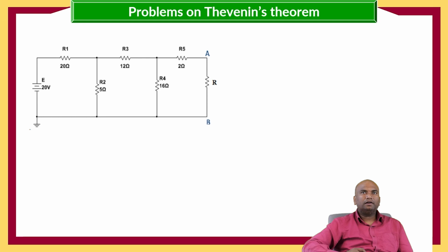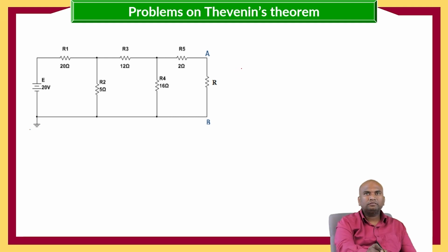Next, we need to calculate the Thevenin's equivalent for this circuit. So here, now for calculating VTH, I am redrawing the circuit. I am replacing the load resistance as an open circuit.